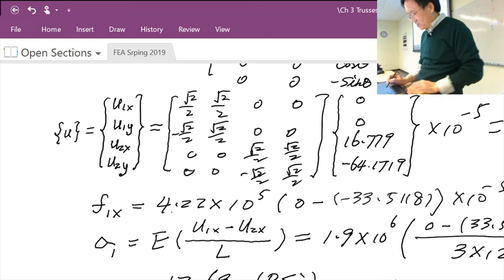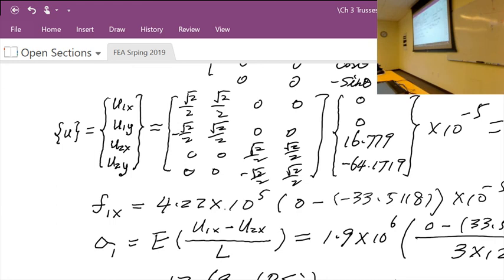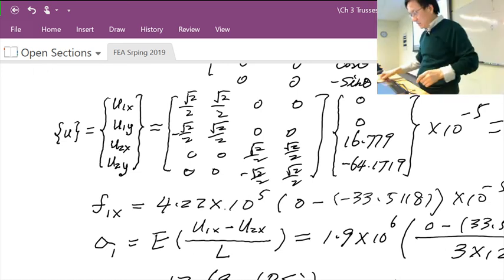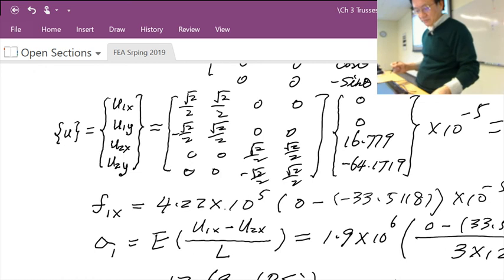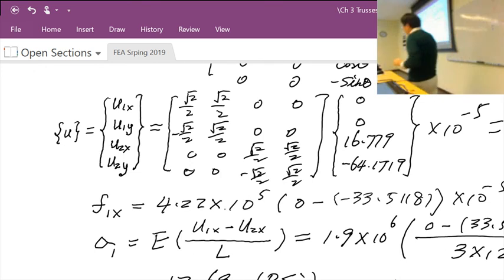If you do a calculation and use the values, you will find the result 141.52 pounds. So if you do a check, the way you use the calculated stress and the way you use Hooke's law, you get exactly the same result. Which means your solution process is correct for element 1. So now we repeat this process for element 2 and 3. Then we will be done with this sample problem.